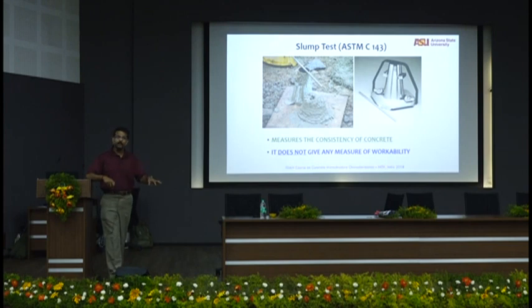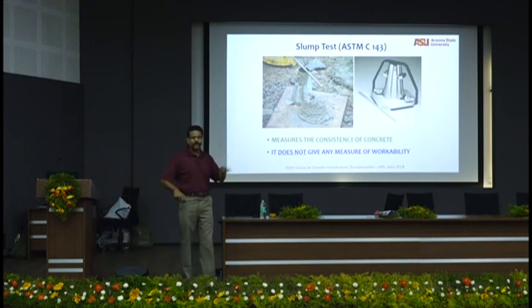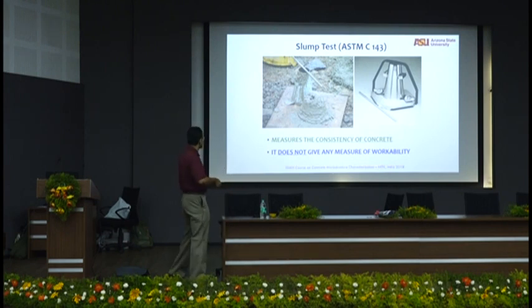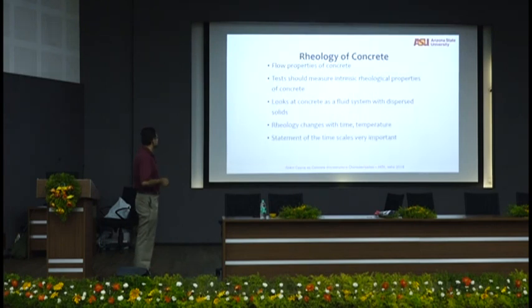Slump test is wrong, and the claim that slump measures workability is wronger, if there's a word like that. Okay, it's even more wrong. So slump measures only consistency, the ease with which your concrete can flow. That also it really doesn't measure; it gives you a fake measurement of what you think happens, right? So this is what your slump measurement is. It does not give any measure of workability, it measures the consistency.